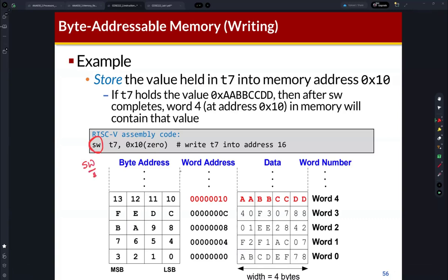You know W, like the load instruction, is 4 bytes. The store instruction also starts with the register number or ABI name of the register, but this register is the source register. The store instruction reads data from the source register, and then this data is transferred to the memory.